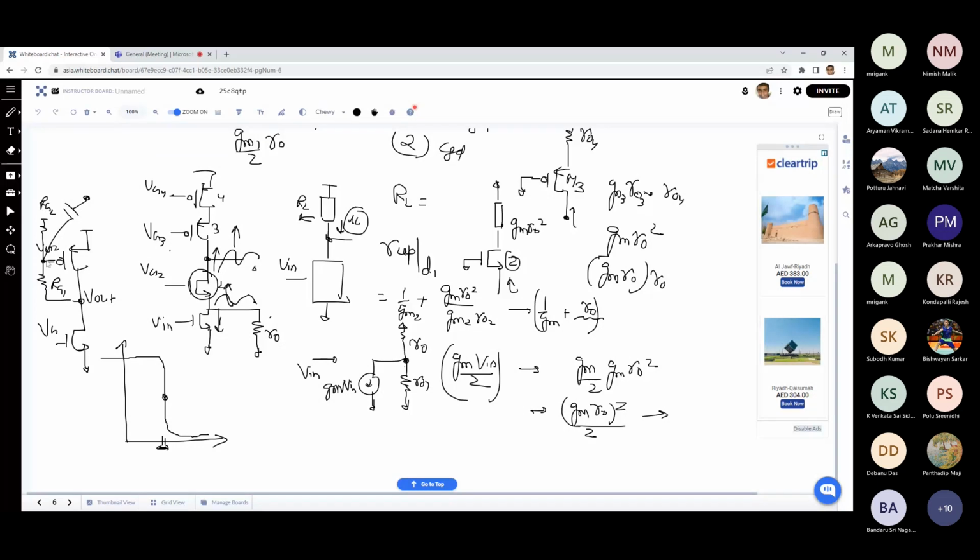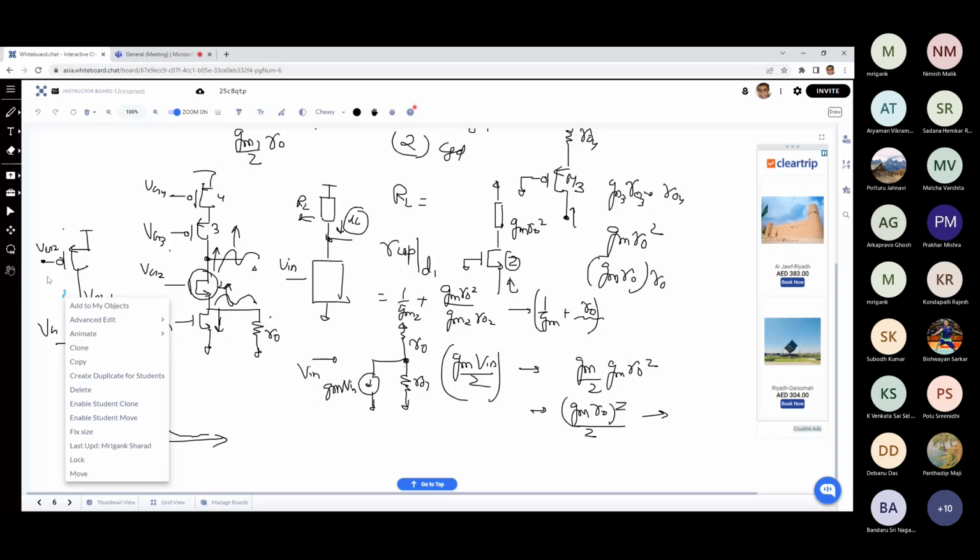Ratios are such that you get a proper VSG for this PMOS, and the DC potential over here will be determined by the voltage division, and that basically helps you in getting the self biasing. But this is not practical for on chip. This is just a toy experiment you can do. But in actual circuits in your mixed signal ICs, this kind of resistors and capacitors cannot be used, especially the big cap. So this is not a plausible scheme.